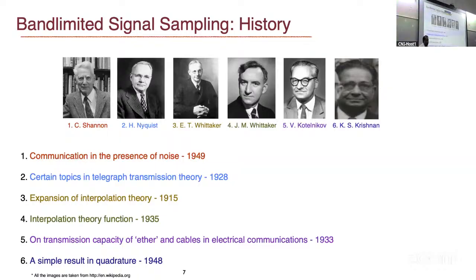This is a standard PhD interview question that we ask every student. You have a signal which we typically say is band limited. That means it has a highest frequency component, and you take your uniform samples at a higher rate. If the frequency is high, take more samples, and then you can get back your analog signal from those samples. That is the standard sampling theorem, right?